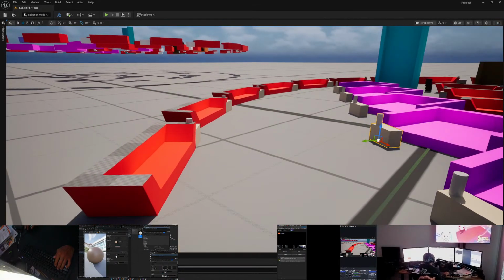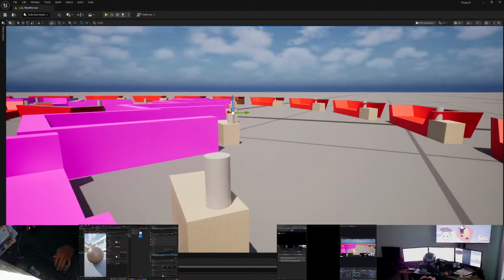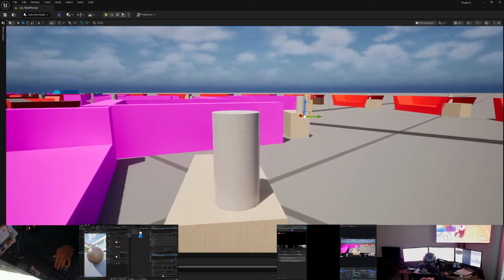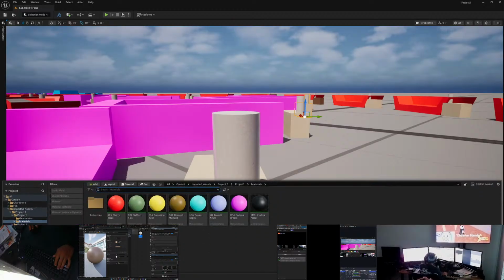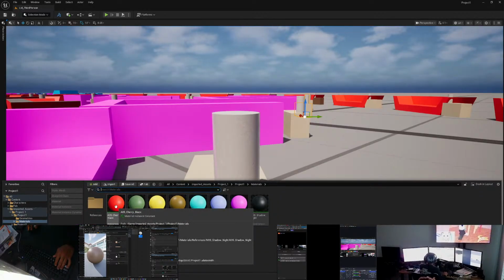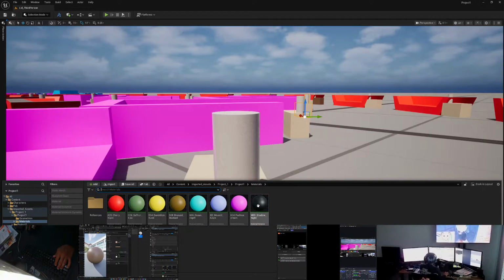But everything's looking good. This is not a great practical example, I don't think, but I think it gets the point across that we're using SketchUp as our foundation for organizing our assets and determining which ones are going to share materials or share meshes. We want to reduce the number of materials and meshes as much as we possibly can. So we still have about 10 materials.